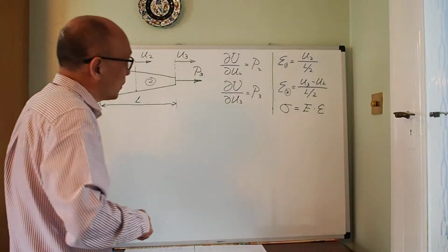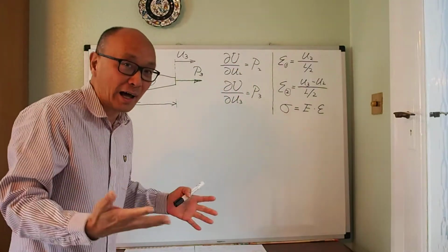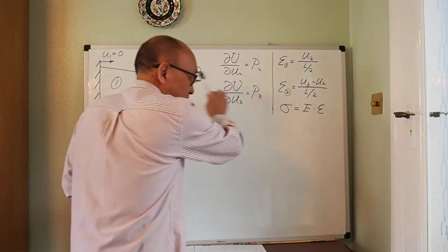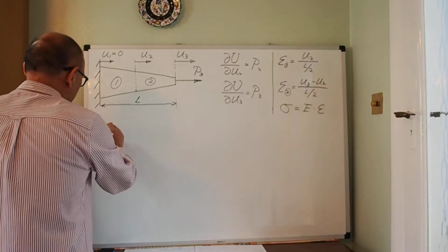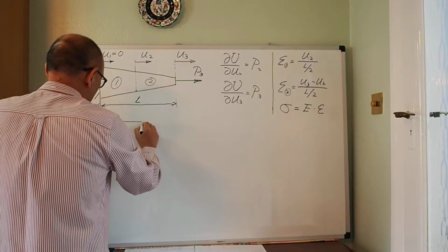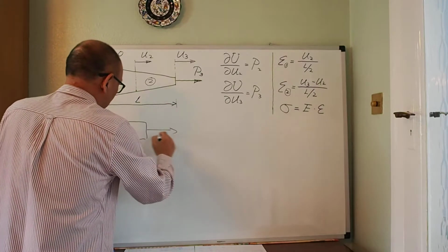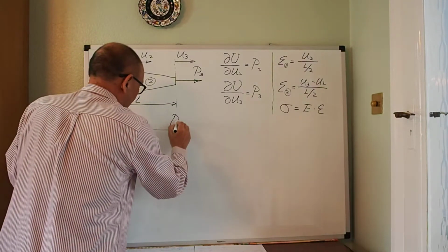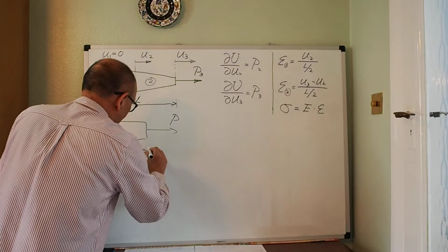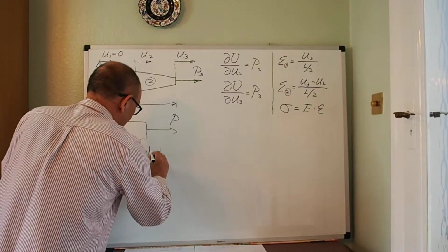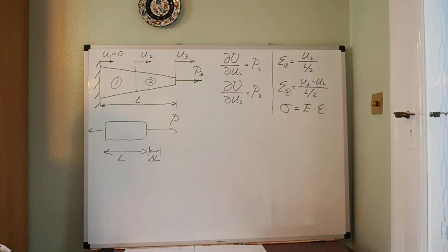What I need to do is calculate the total strain energy. Once I've done that, the problem is solved, I just follow the logic I've just explained. To calculate total strain energy, let me simplify the problem a little and consider a uniform bar. If I apply load P there, and its length is L, it gets a bit longer, changing length by a small length delta L.